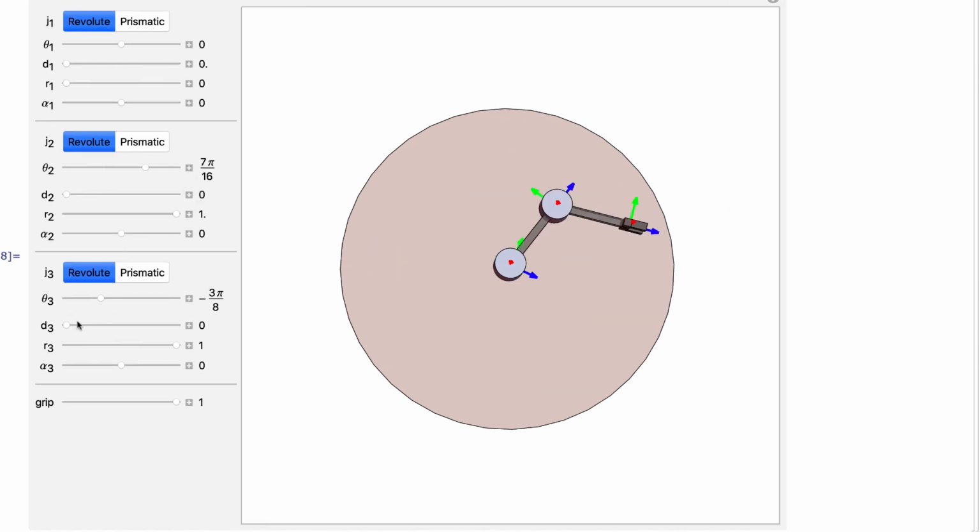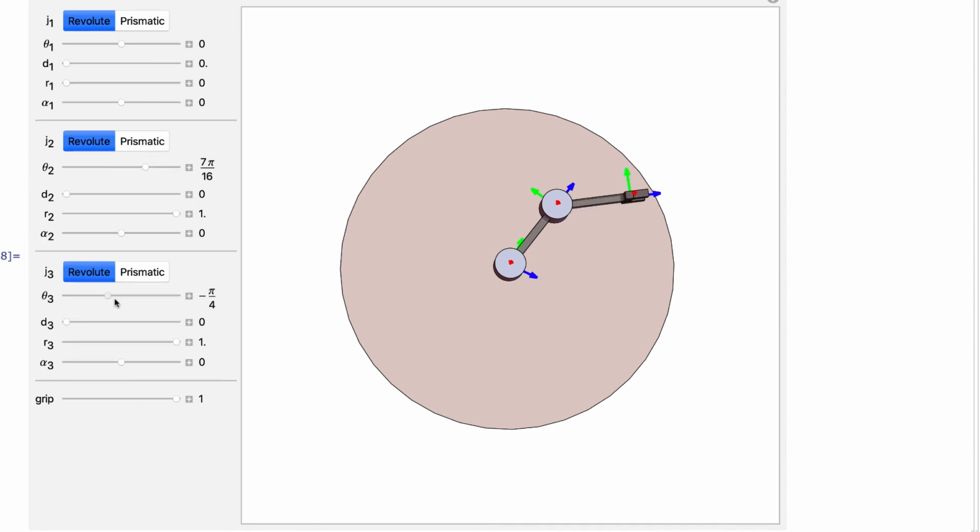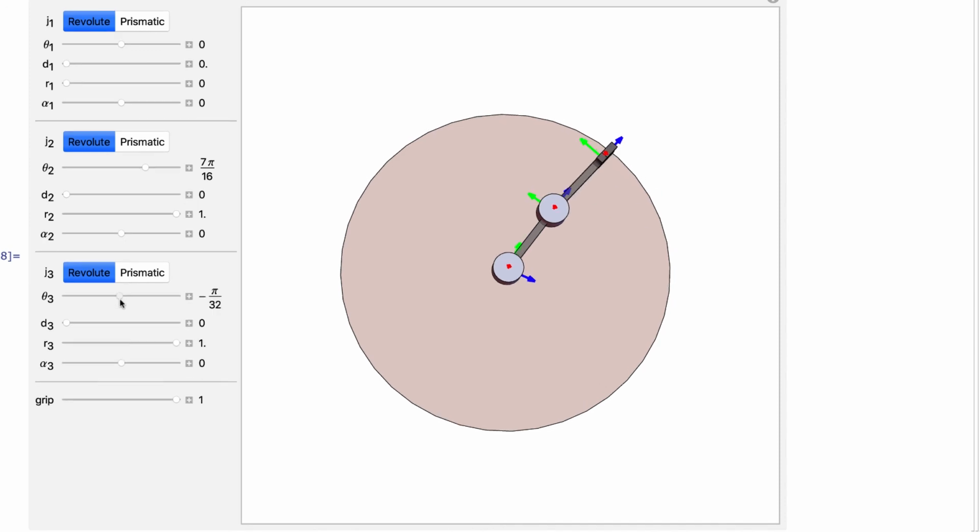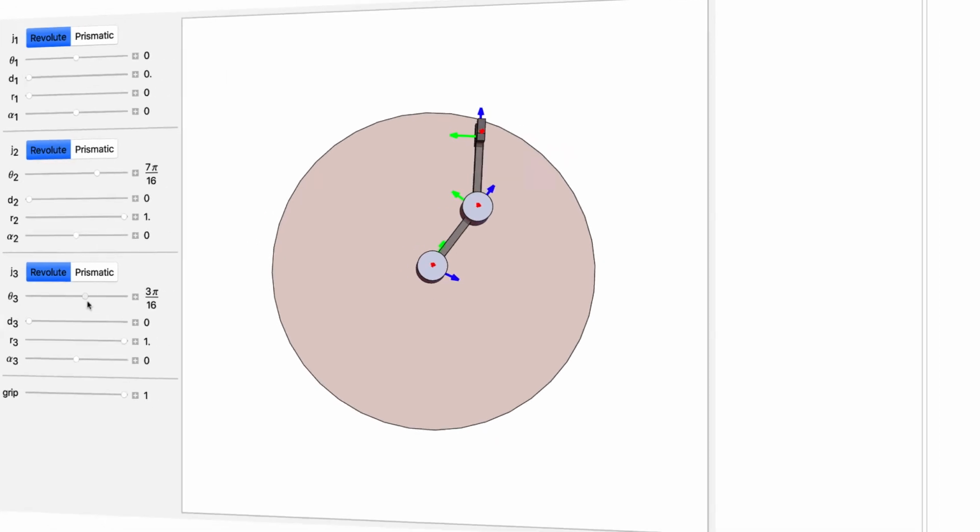similarly for my next joint, it's got some radial distance that it offsets to the end effector. Everything else is 0 except my revolute joint. And so if I set this revolute joint to 0, they're aligned. Then as I increase that, it rotates around that point.